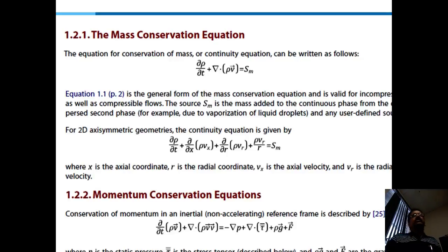Once you discretize it, you can pick a particular cell and say somehow magically some material is appearing there, and you can inject it. So you can have a source, you can have a sink if it is negative. Okay, so that's a very general formalism that allows you to specify source and sink in any boundaries or any interior domain.